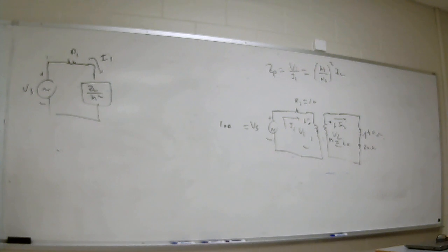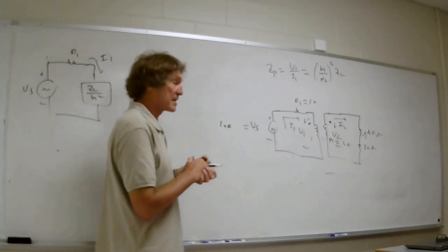The load circuit, the impedance will reflect down as 1 over N squared. No, I'm just wondering if I wrote the formula wrong, like if I derived it wrong. I think I just did it backwards. It's always the more turns, the higher the impedance. Think of it that way.